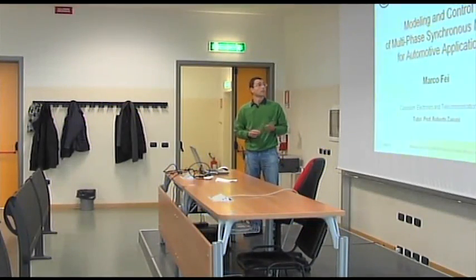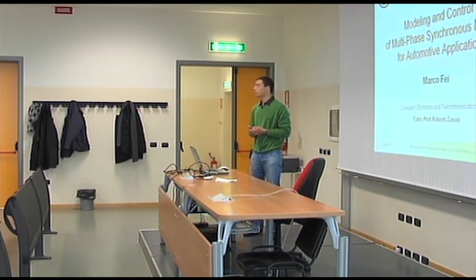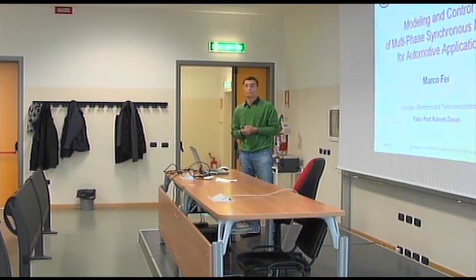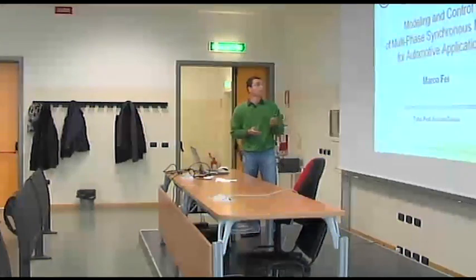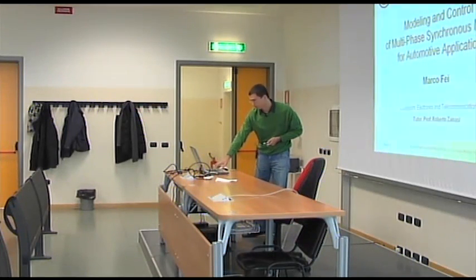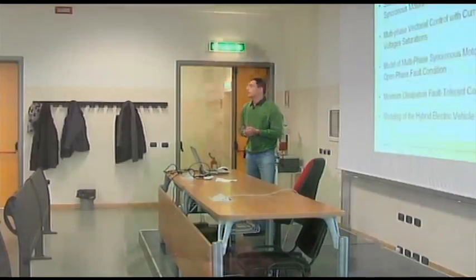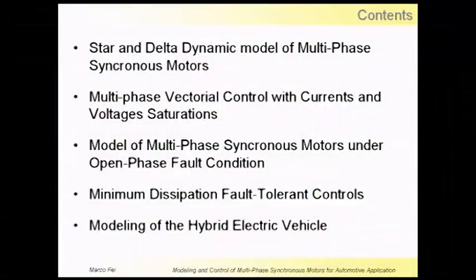Good morning to everybody. My research activity is focused on the modeling and control of multi-phase synchronous motors for automotive application. The fault-tolerant capability of the multi-phase motor drive and the possibility to enhance the motor torque by injecting higher-order stator current harmonics make the multi-phase synchronous motor suitable for electric and hybrid applications.